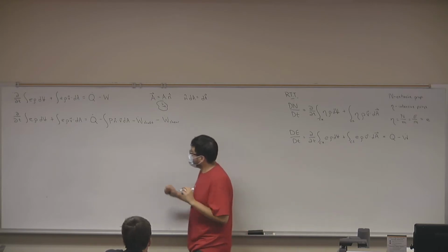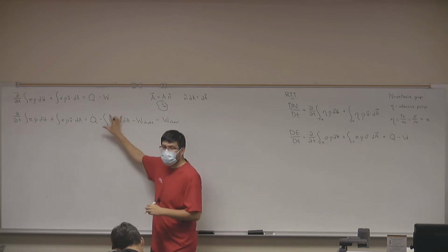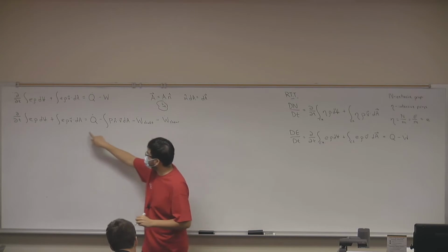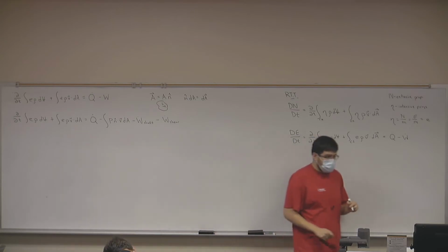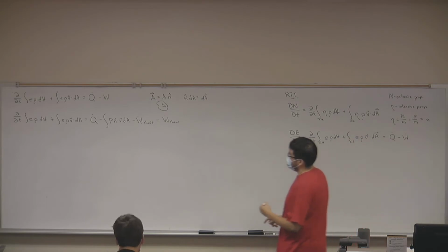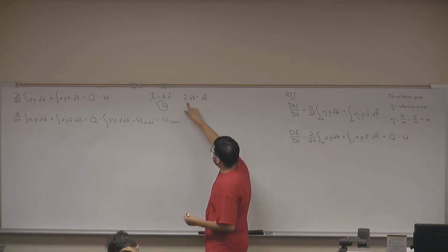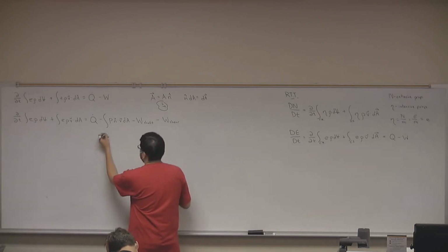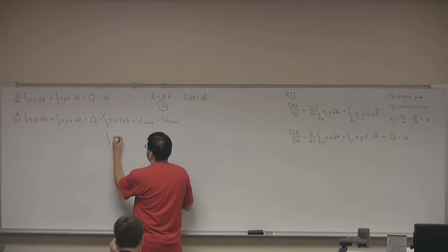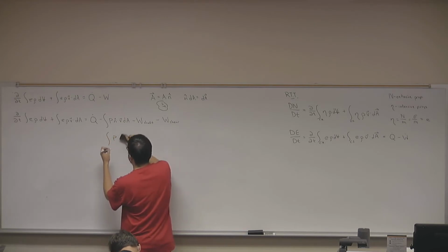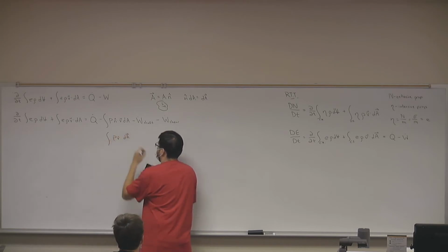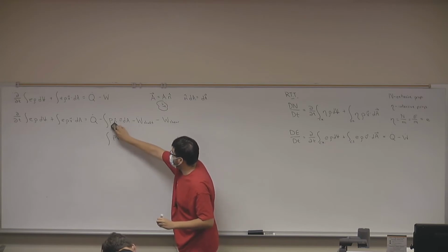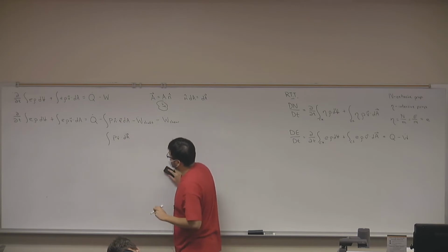And the reason I'm doing this is because now, hopefully you'll see why I wanted to separate pressure. Now I can express this integral in the same way that I'm expressing the flux integral. So this will make my life a little bit easier. If we set that n hat dA is simply the area vector, what I get is this entire equation, but here in the integral term, I'll have the integral of p dot dA. Because now we are moving this vector, combining it with the area. So we still need to take the dot product of this vector and the velocity vector, but now the vector is actually the area vector.